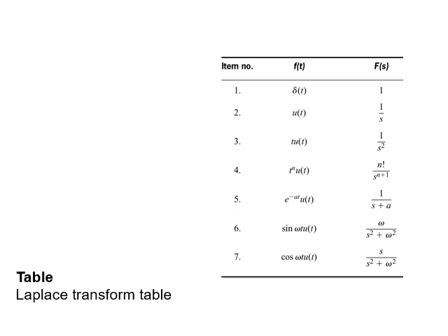For delta or impulse, we have a Laplace transform of 1, for step 1 over s, for ramp 1 over s square, and so on. Similarly, for parabola it can be found with the relation given in item number 4, and similarly the Laplace transform can be found for sinusoids given in item numbers 6 and 7.